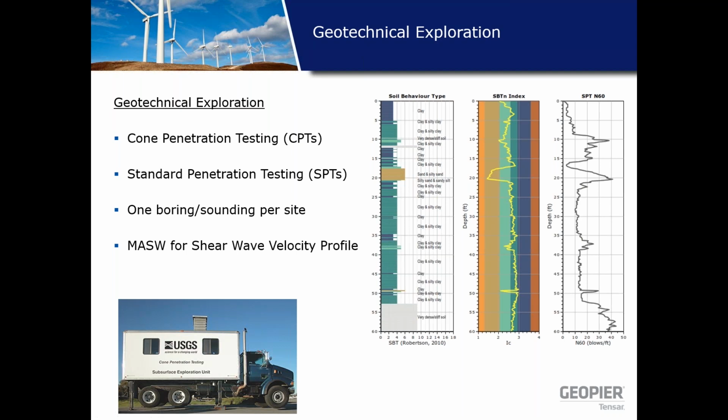Now, when these borings are performed, you need to make sure that you're getting enough subsurface information to properly design the foundations. Sometimes that's to a depth of 2B, sometimes it'd be to refusal. Really what you should do is use the local standard of practice.